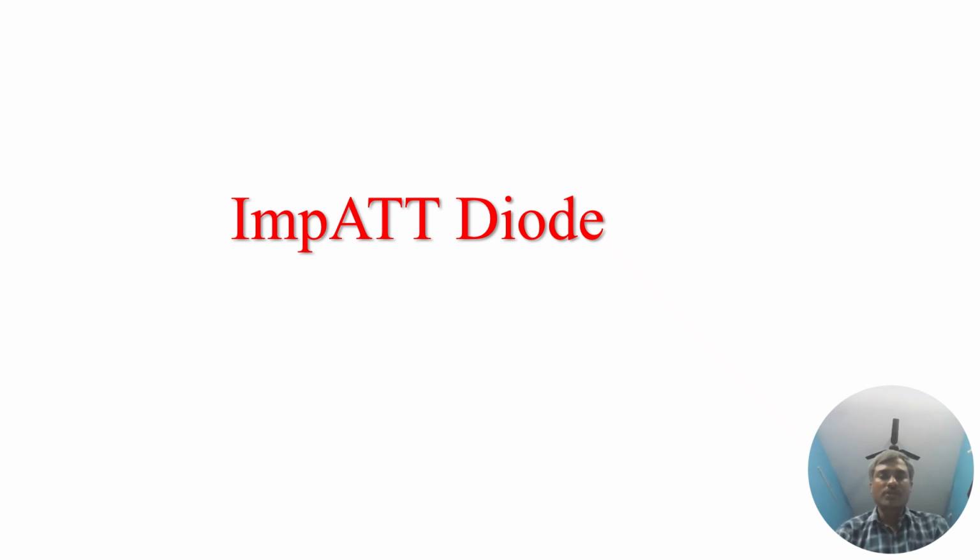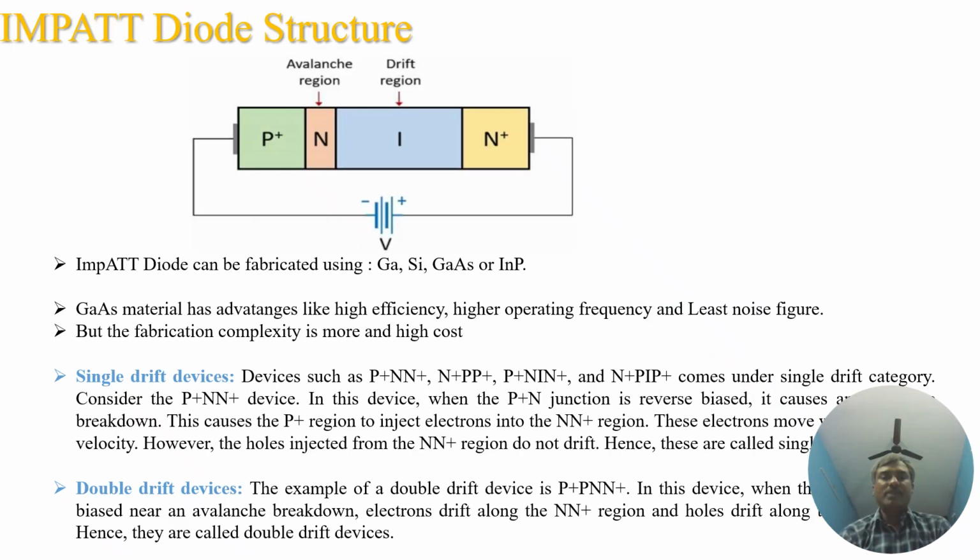Hello students, now we are going to discuss the construction and working principle of the IMPATT diode. IMPATT stands for Impact Ionization Avalanche Transit Time device. It mainly works on the principle of impact ionization and avalanche multiplication of charge carriers. An IMPATT diode can be fabricated using germanium, silicon, gallium arsenide or indium phosphide.